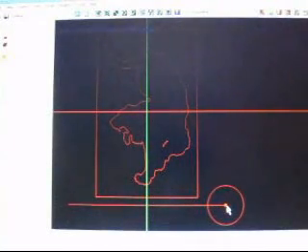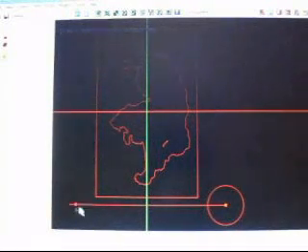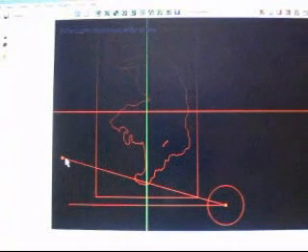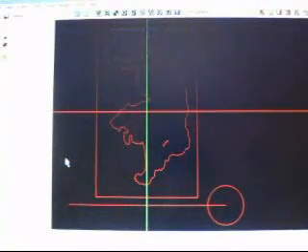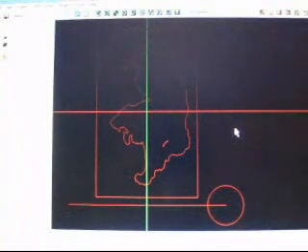Select the line, I went to this point and dragged it out to here, to the end of that, and hit enter. Okay, I'm not going to do that because I already drew it. It's not a big deal to draw a line, okay? But if I drew the line from left to right, it would have an impact on how the thing would be machined, and that's what you need to know. Okay, I just wanted you to understand that.